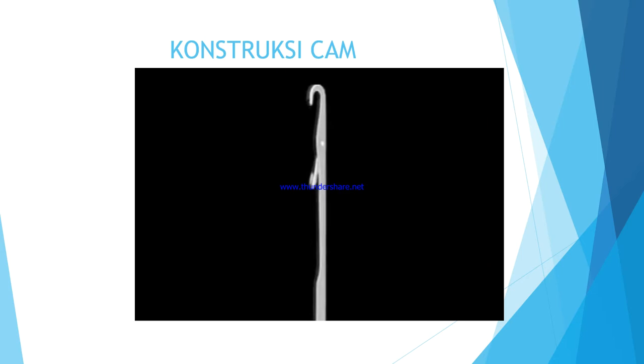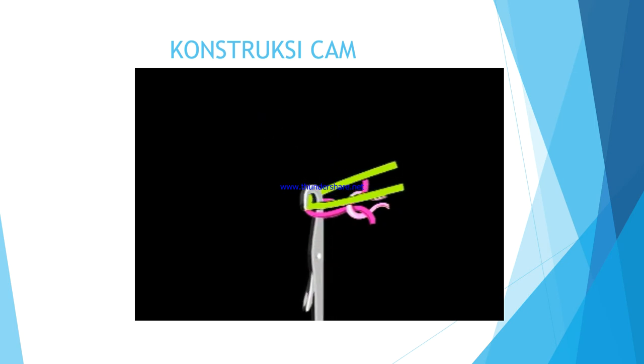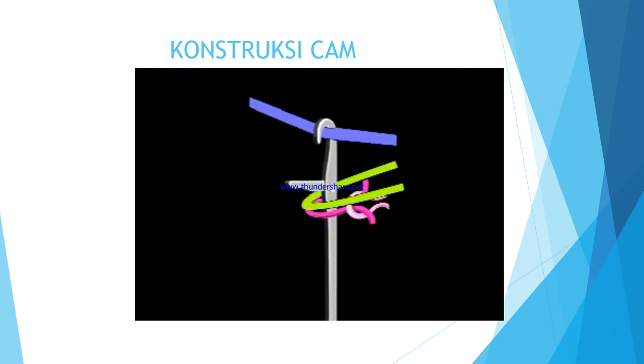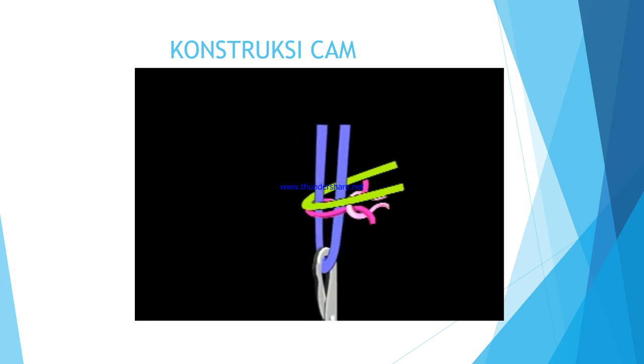During the tuck cycle, at feed 1, the needle moves up from its rest position, and the old stitch that has been formed is held and not allowed to clear the latch. Yet the needle moves up far enough to grab a second yarn, which is put into a tuck position. Both yarns are then kept at the rest position. The knit cycle occurs with the next feed of yarn. At this time, both yarns are cleared. A new yarn is fed and pulled through both the held and tuck loops, forming a tuck stitch.